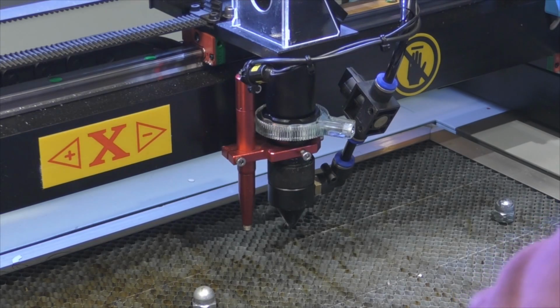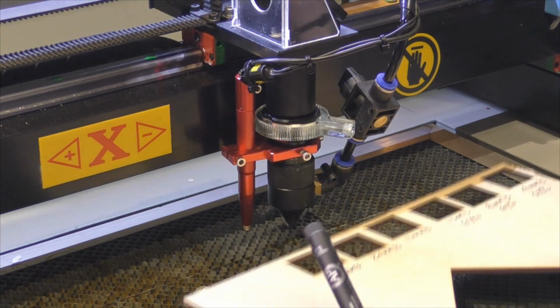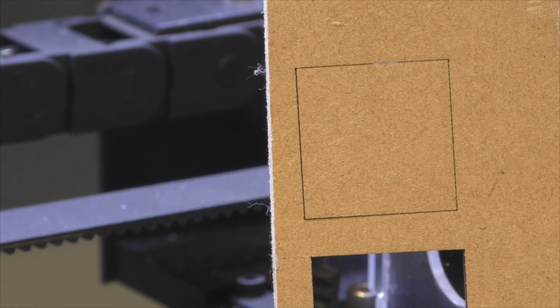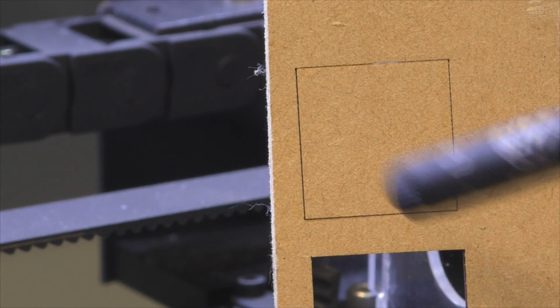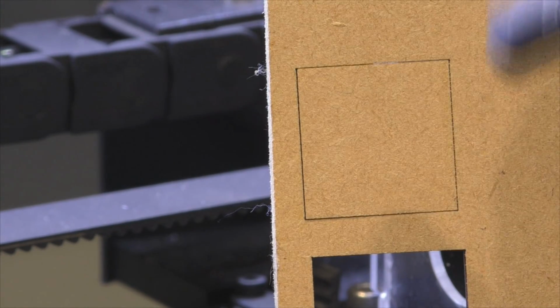We have reached a limit, but what we'll do, we'll go beyond the limit, 22 to 24. We could say that this is actually cut. It's done a superb job on the underneath here, and that's another trick that I will point out to you. You don't always cut a product like this face side up. It's often better to cut it from the back, because the back side is often extremely clean like this. Yeah, and that's just hanging in on the corner.